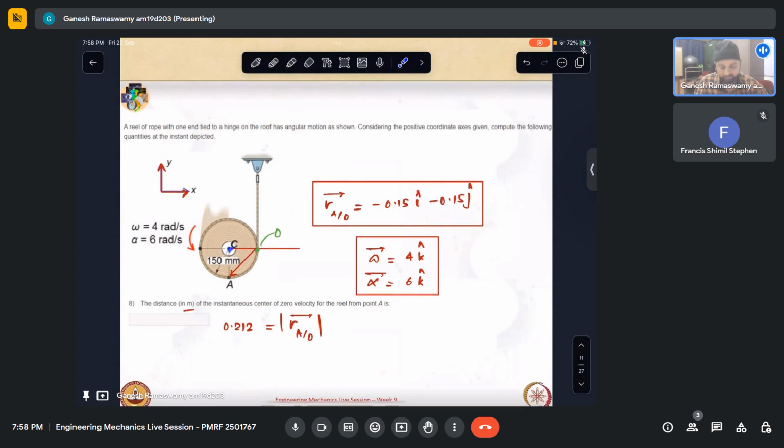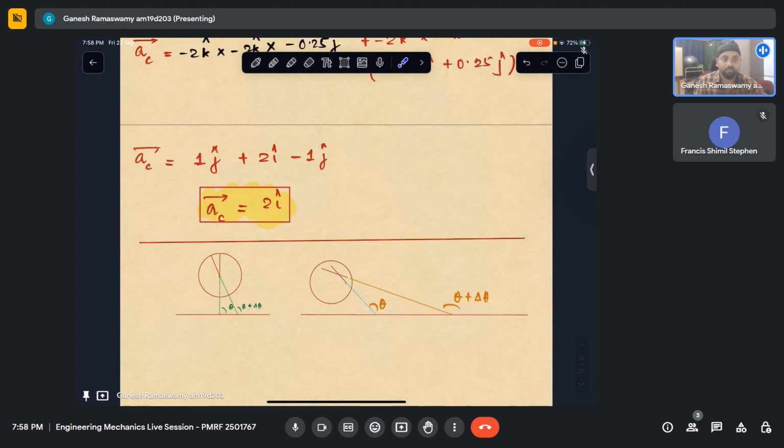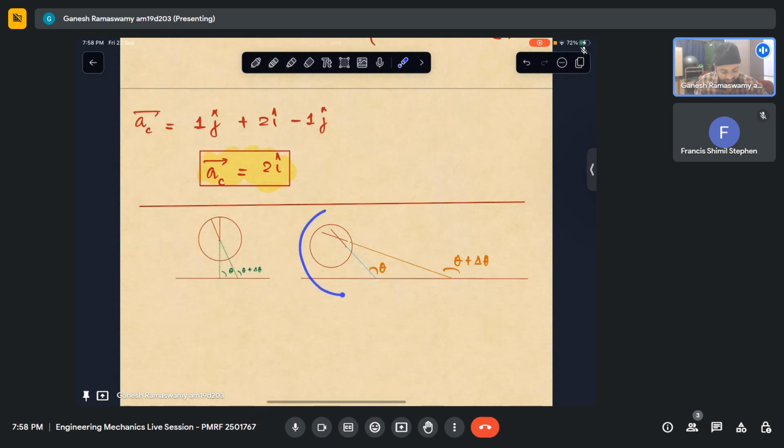The other way to go about it is that we fix it to the center, then we need not actually bother about calculating the acceleration unless that point has an acceleration. Another way to say this is that if the rolling disk does not have any angular acceleration, then the center's acceleration will be zero because its velocity is only linear. And we saw how scribing a line on two disks is tantamount to evaluating its velocity. So we are not constrained to have our lines parallel like spokes. It can be any line. In fact, this is what we thoroughly apply in our rigid body mechanics because not all objects are circular.